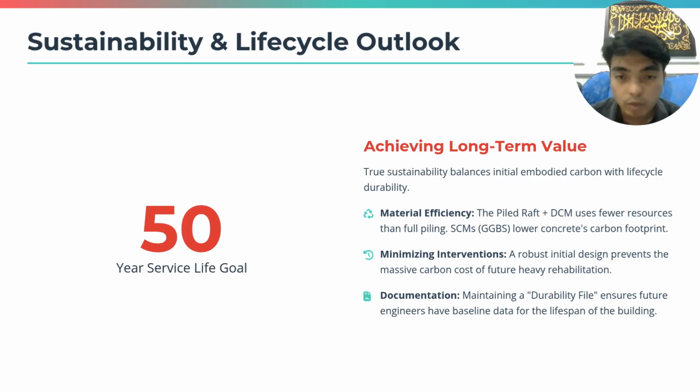If the foundation is moving, we stabilize it first, perhaps via grouting, before repairing the structural concrete. True sustainability is balancing the initial green materials with long life durability. Preventing one major repair 20 years from now saves more carbon than any specialized cement can offer today.